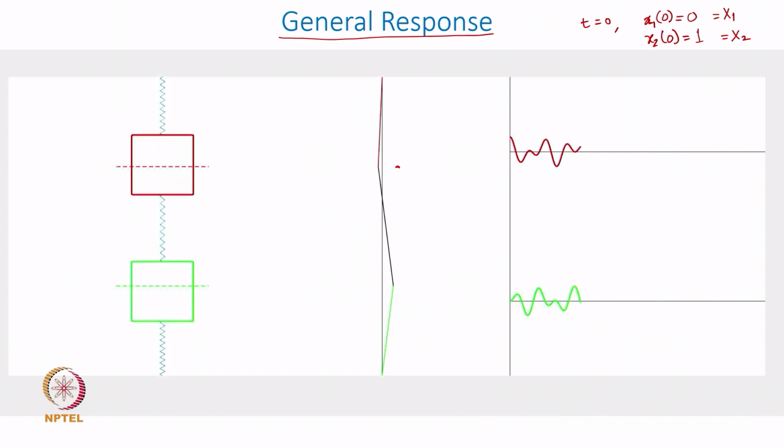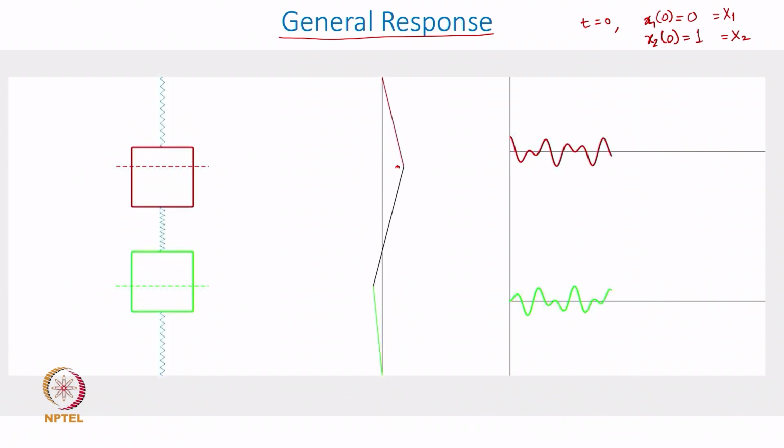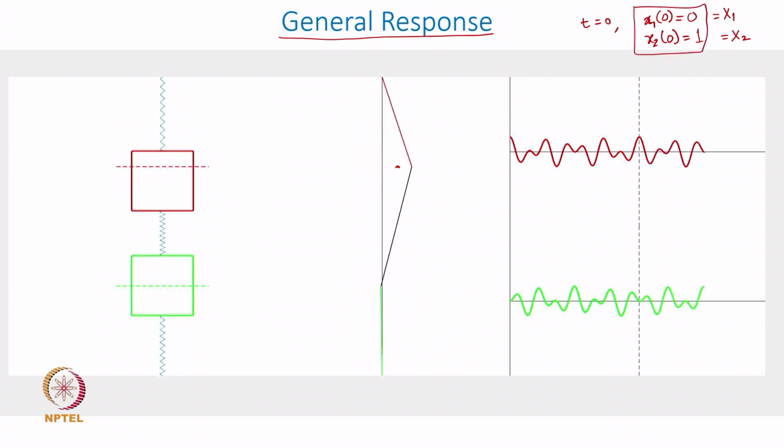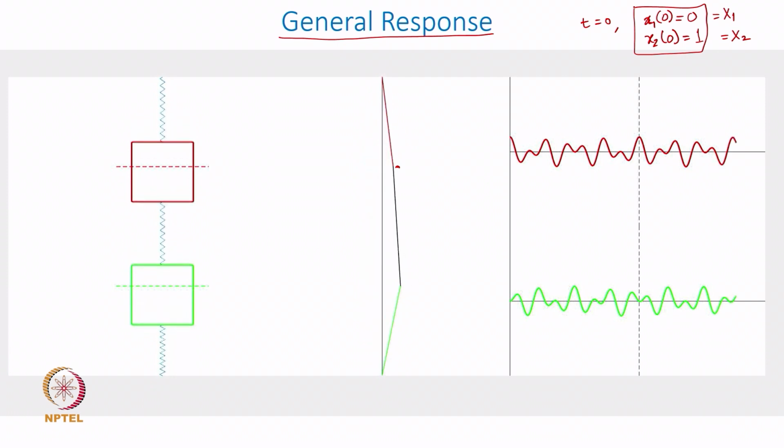You do not see a harmonic motion happening, right, and it is all because you have not maintained the initial displacement same as, or honoring, the mode shape, either of the first mode or of the second mode, okay. And that is why the motion that you get is a mix of the two harmonic motions, okay.